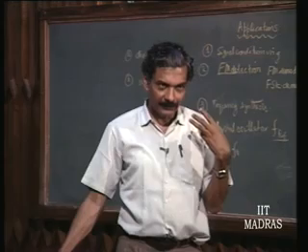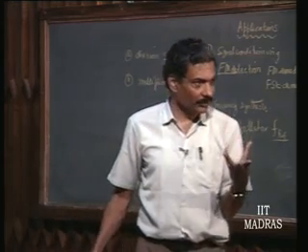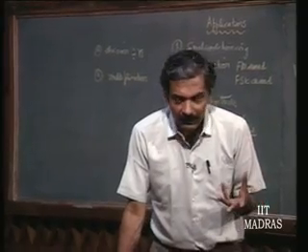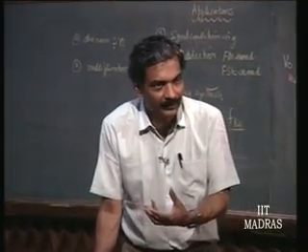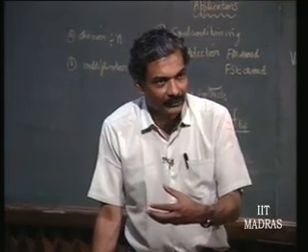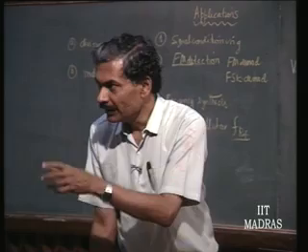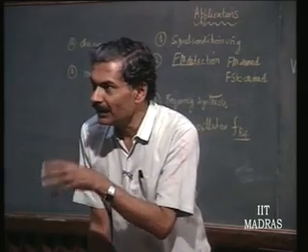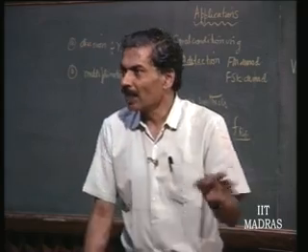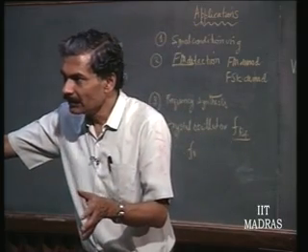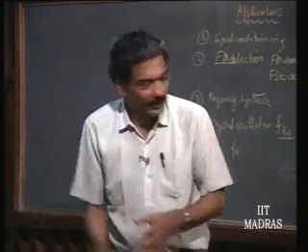Microwave engineers, when they were confronted with this problem of frequency synthesis, used diode nonlinearity. Okay. Diode is a nonlinear device. Okay. And therefore, they fed this signal to the diode, and output of that had lot of frequency harmonic components, and they could filter out the desired frequency component. But this is a very inefficient way of doing, okay, because harmonics will be reducing in amplitude as you try to select higher and higher harmonic components.